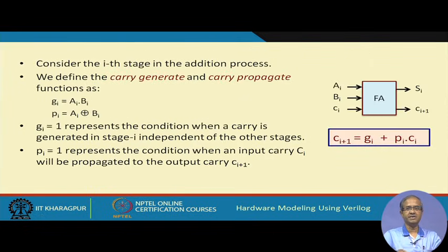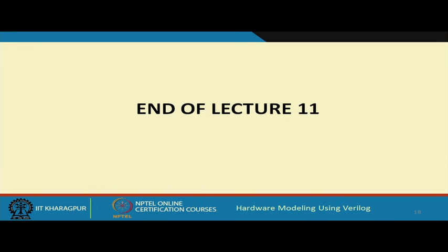So, in the same way as I said, you can replace a module by a better or an improved module. For example, we replaced a 4-bit ripple carry adder by a 4-bit carry lookahead adder. We have got a faster adder, but we can do simulation and find out that functionally our design is correct, it is working correctly. So, this actually completes our discussion for today's lecture.